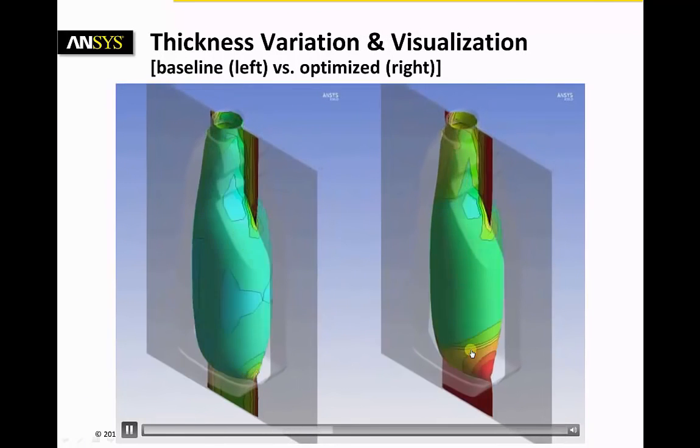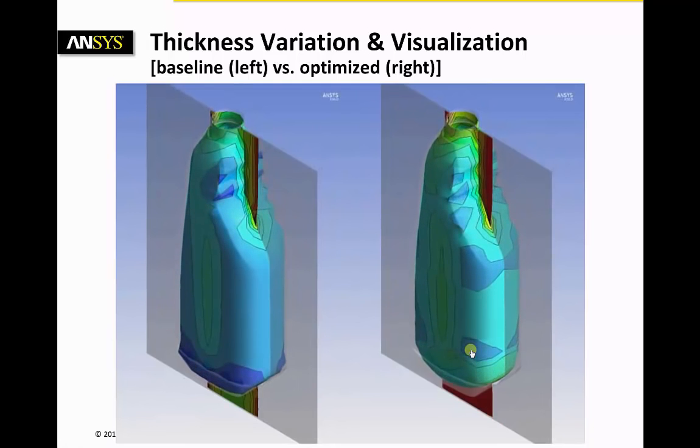The extrusion blow molding process is simulated. Two different settings are shown: a baseline setting on the left-hand side and an optimized setting where the initial thickness of the preform is adjusted so as to meet a predefined final thickness variation. This allows for a smarter bottle where the thickness is adjusted where needed and thin where not really required.